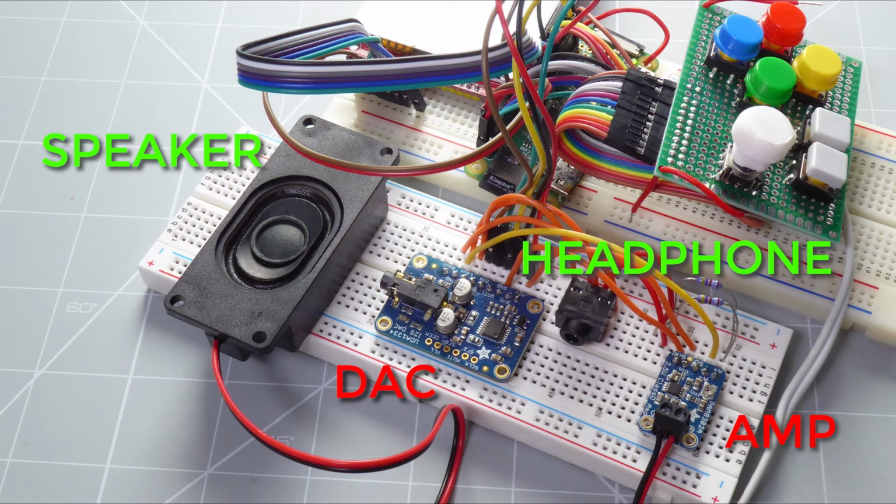So the amplifier module then is, I'm going to use a mono amplifier, and this is the same as the one we used for our analog sound in the previous tutorial. So we do need to take the headphone signal. We then need to use two resistors to combine that into a mono signal, and then we can feed that into this mono amplifier, and of course that then powers our loudspeaker from there.